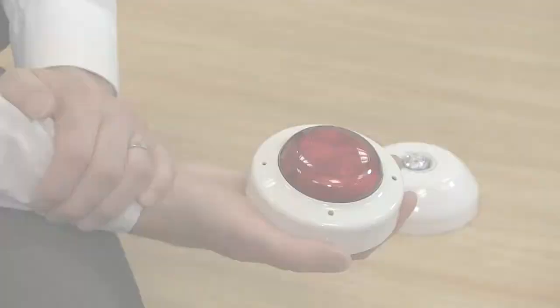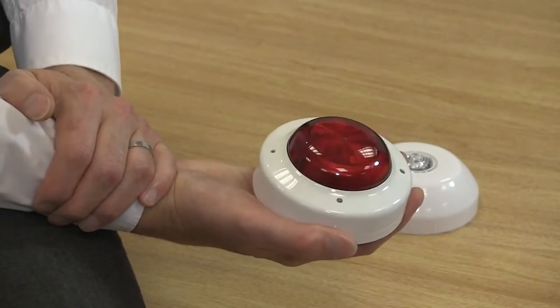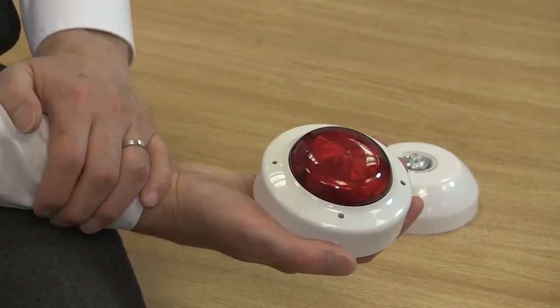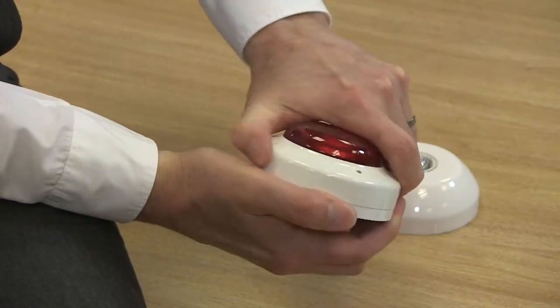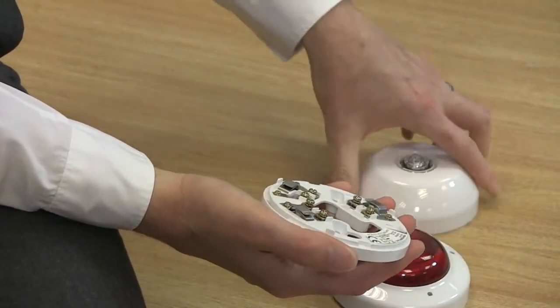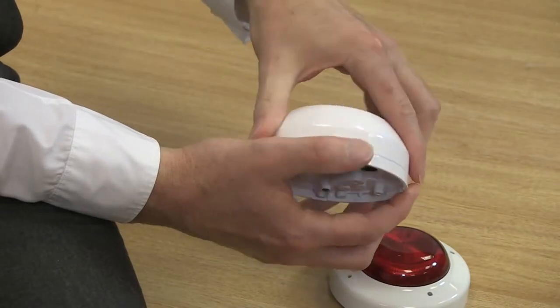By the way, don't worry too much if your panel software isn't up to date. The ceiling beacons will work right out of the box at a default coverage of 7.5 meters diameter, and the wall beacon default is 6x6 meters. The large open area ceiling beacon default is 15 meters diameter. Both devices have been designed to fit onto our standard mounting base, and because of this, the new ceiling beacon can directly replace our existing beacon, the CHQ-AB, as it has the same product type code at the panel.